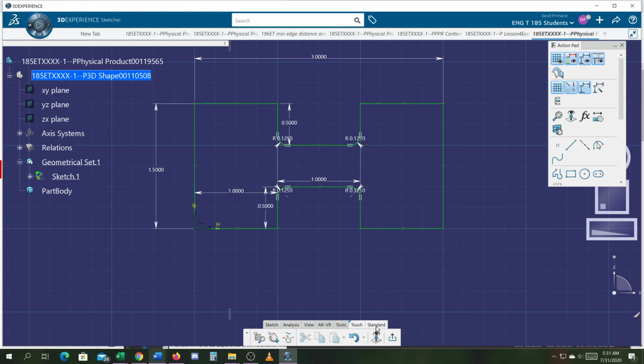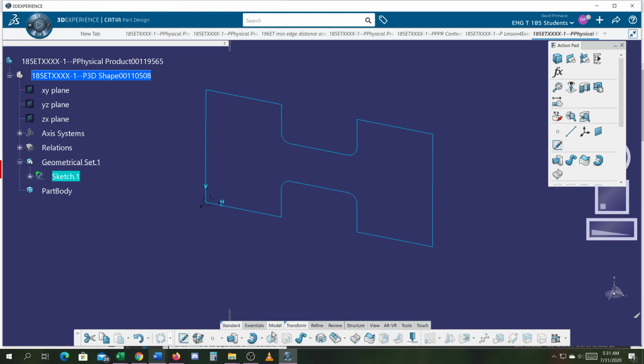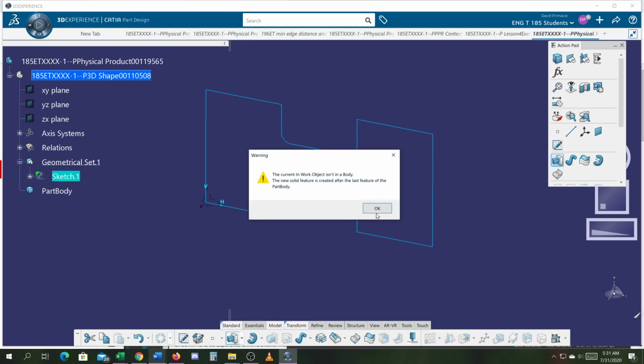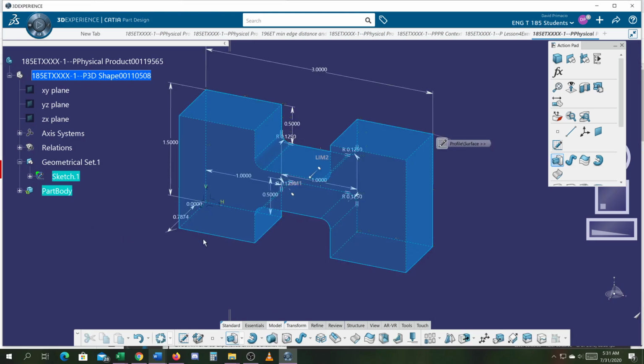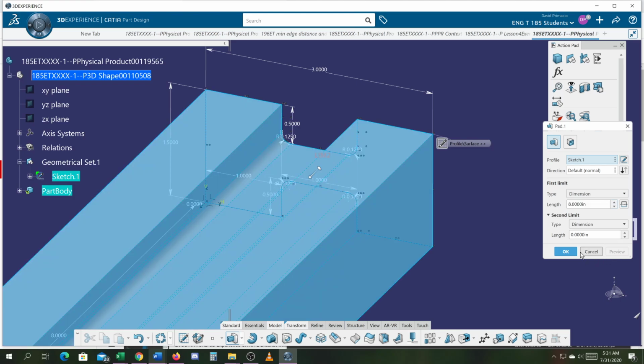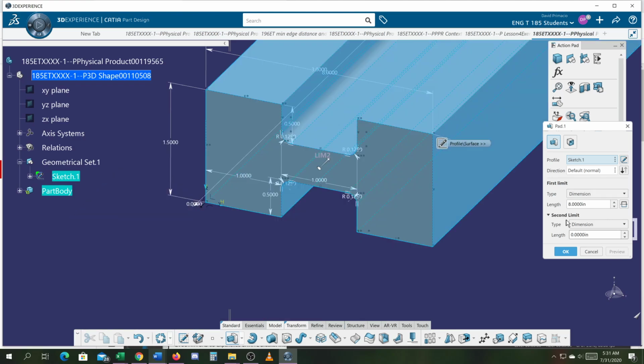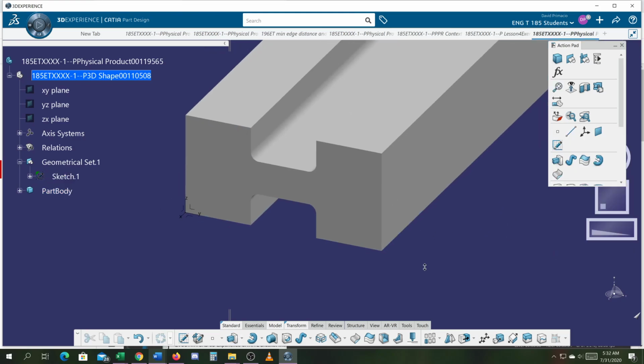Okay, so you should pretty much be able to do the rest, but I'll go ahead and continue here and make a pad. Oh, forgot to move the sketch. Let's just go 8, preview, reverse the direction, select preview. Now all my numbers are on the front, select OK, and there you have it.